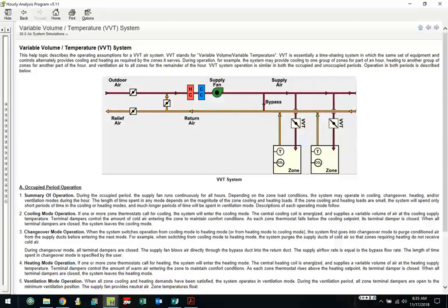And as I'm doing that, and the duct pressure gets past a certain threshold indicative of not having enough airflow, we would go ahead and index or open up a bypass damper. So again, if I'm in heating and I'm putting out 105 degrees, 100 degree air coming across here, and I don't have enough airflow, let's say out of the 3 boxes we can't see, another one closes down, and now we're down to 2 of them, we would start bypassing hot air into the return stream. Some of it would go out in relief, but some of it would come in here. So now we're preheating the air going into the coil, which makes my delta T even lower.